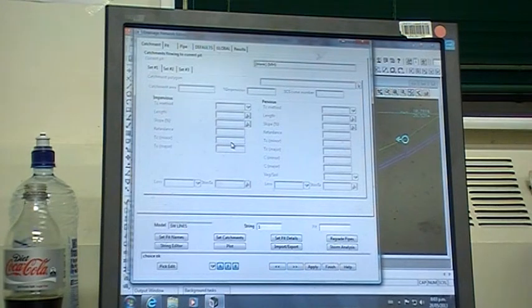There is one major exception to that. I'm doing a subdivision up at Snells, in fact, the one that we've been working on at the moment. The upstream catchment, which is always the responsibility of a developer, is quite often a problem because they've been under-designed, either through negligence or because things have just developed beyond what the original design was going to be, and you end up with more stormwater coming downhill than can fit into a pipe.